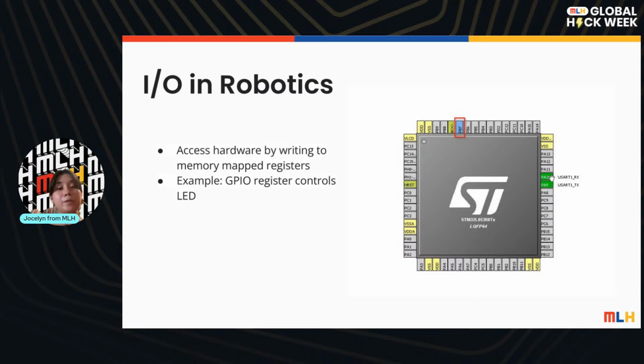But now, what happens when you are trying to configure those ports in a more complex chip in the low level format? So with libraries and components like Arduino, you just manually select the pin that you want to use. You just say, okay, I'm going to use pin 7, and that's it. But when you're going into STM32 and how to configure those pins from the backside, there's some bit manipulation that you need to do in order to configure your pin correctly.